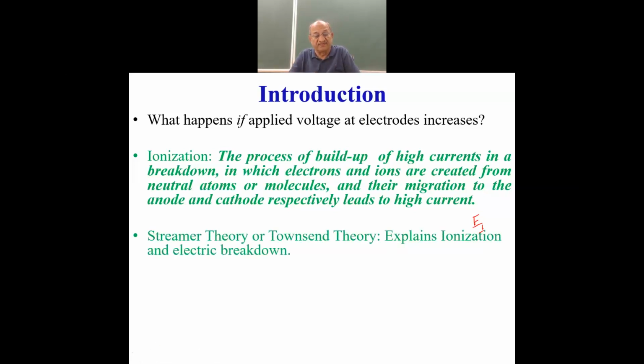Next, the ionization actually develops in the form of an avalanche. We learn what an electron avalanche is, which comprises the electrons, and when the electrons are formed because of ionization, it leaves behind the positive molecules. So the molecules and electrons together grow by increasing the voltage in the form of an avalanche.